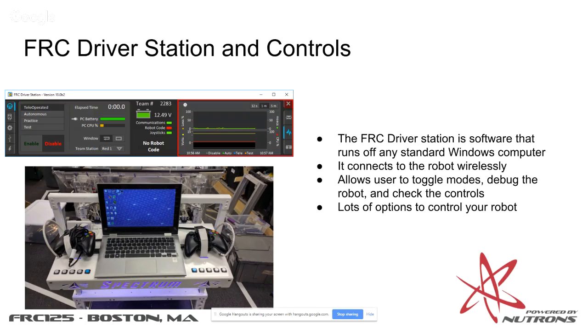This last year, we had an issue where it was physically impossible for us to test it until we connected to the field. In the driver's station we had our autos for the left and right push scale positions already in there. But we were calling for them when the robot initiated instead of when autonomous initiated. So we were calling for values that didn't exist when the robot was first connected. They didn't exist for auto. It worked fine when we were at home, but as soon as we connected to the field, it didn't work. We had to figure that out.